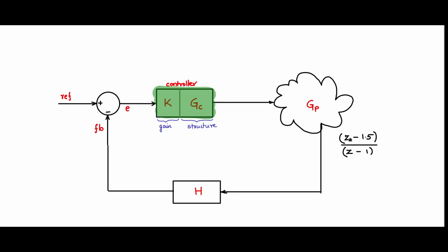So 0 can exist in the unstable region, but the pole cannot exist in the unstable region. So that is an unstable system. But you have several realizable plants, several practical systems where zeros are in the right of the S-plane in a continuous domain, or outside the unit circle in the case of the discrete domain models.